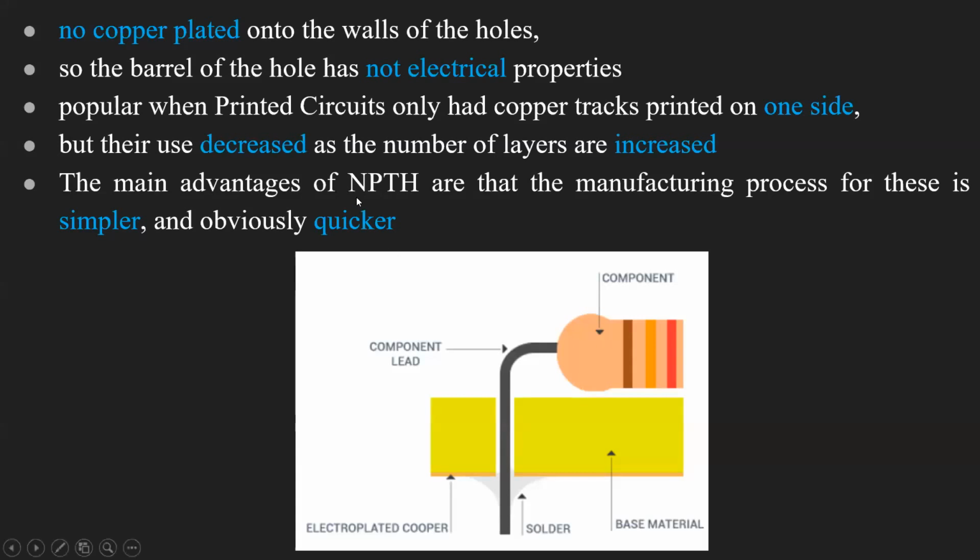The main advantage of NPTH, as I explained, is that it is simpler and quicker. You can manufacture this PCB very quickly because the solder does not have to be sent through the whole barrel.